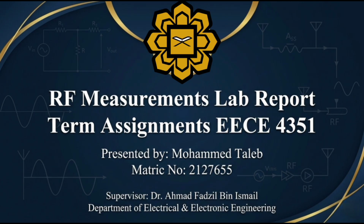In conclusion, these two experiments give us hands-on experience with essential RF measurement tools. We learned how to measure antenna matching using S11 and how to generate and analyze RF signals. We also understood the importance of calibration, impedance matching, and instrument limitations. Based on our results, we can now judge whether an antenna is well matched and suitable for its intended frequency band.